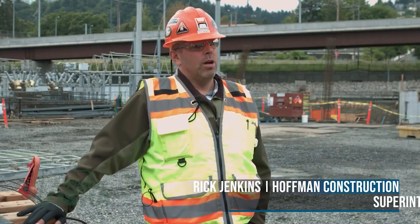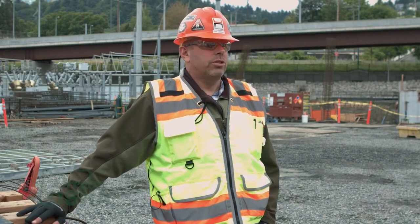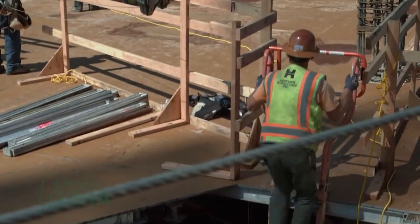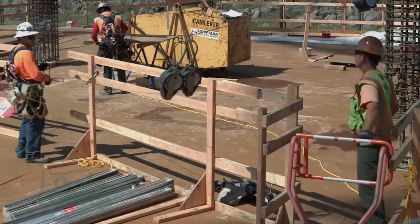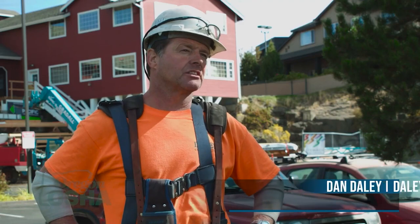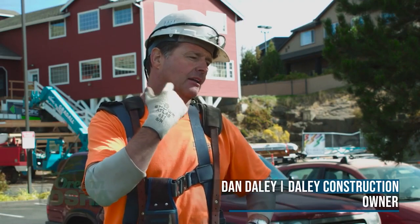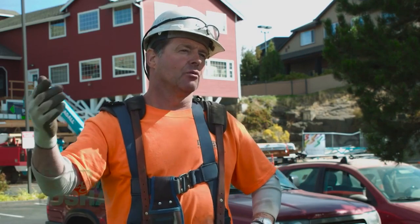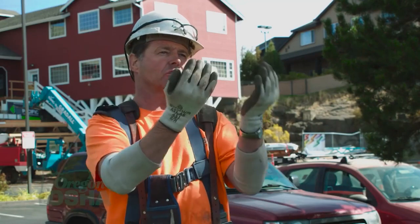When I run projects and set up activities to happen on a construction site, we will always try to be in fall protection. Top rail, mid rail, toe board, and naturally you on the common sense side of that assembly, because it essentially eliminates fall arrest. Usually we use them around holes in the floor system. Like when we're building a second floor system on a building, we'll be tied off wearing our fall protection till we have the perimeter wall stood.